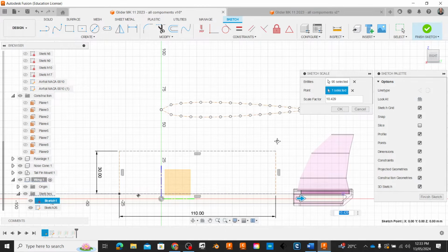So this is where it gets really satisfying, because you can actually see your work kind of coming together. So I'm going to loft these wing parts from the outside in. If I look at this from the right-hand side, I can see that all of my wing profiles are within that box that I created to begin with. Yeah? So I know that it's going to work for me when I put it into the CNC. So here, I'm going to go Loft. I'm going to click on this profile and this profile. And then I'm going to go OK.